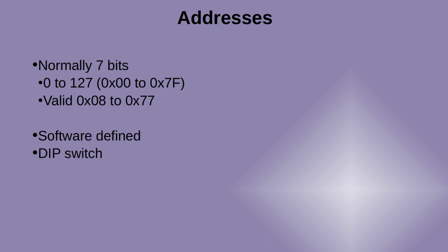Some devices may allow you to change the address using a dip switch or a jumper. Usually these will have a reduced range of addresses that can be used, but by selecting appropriate values you can get multiple devices to work correctly. Next is that some PCBs have small pads that can be soldered to, or where tracks can be cut with a knife. These offer a small amount of flexibility. It's okay when you only intend to use the PCB in a single setup, but isn't so convenient if you need to change the address.